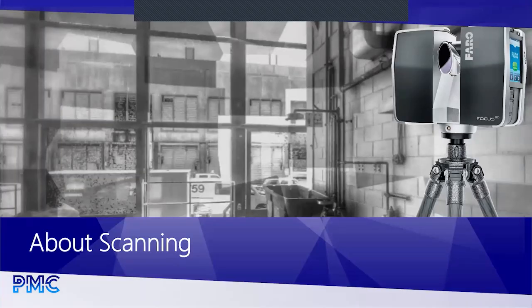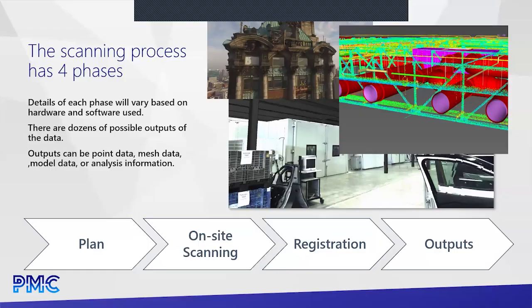Okay. Jump into a little bit about scanning. So the process really falls into 4 steps, right? The first one being planning, where we'll plan out the job and schedule everything. Then the on-site scanning. This is where we're actually going to physically show up at the site and capture the data. Once we leave the site, we have to post-process or register the data. This varies a little depending on the type of equipment that was used. And then we have to generate whatever the outputs might be, whether those are just scanning outputs or CAD outputs or analysis outputs.